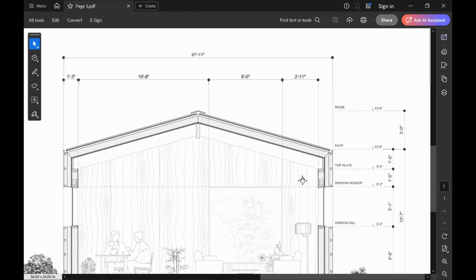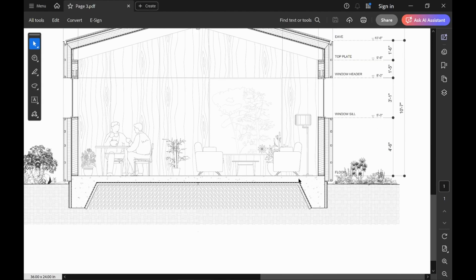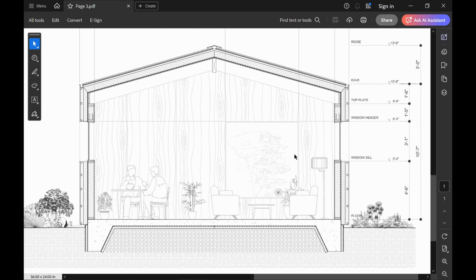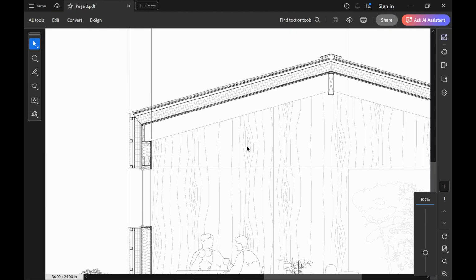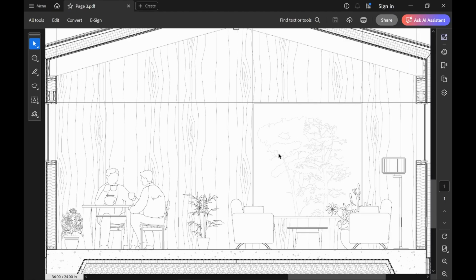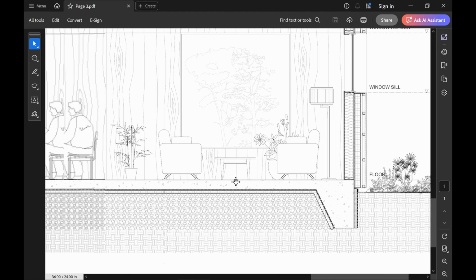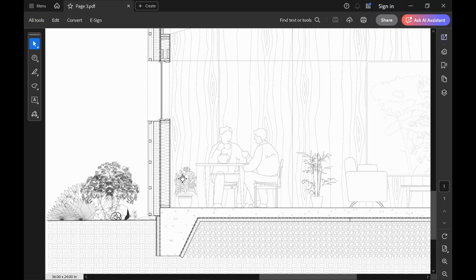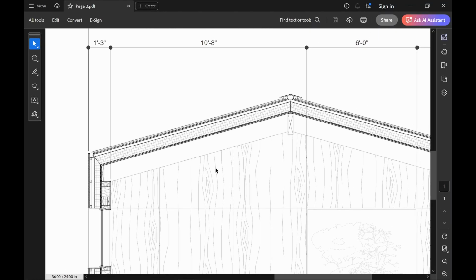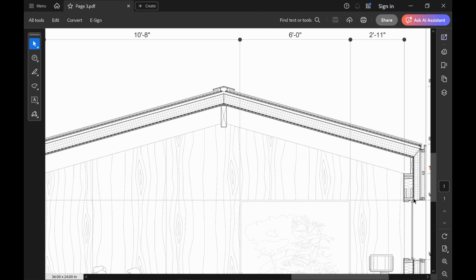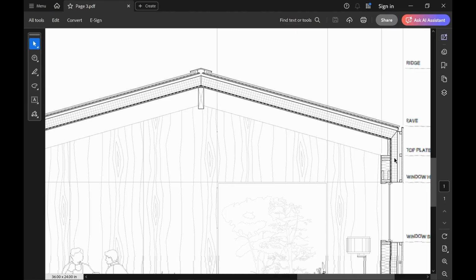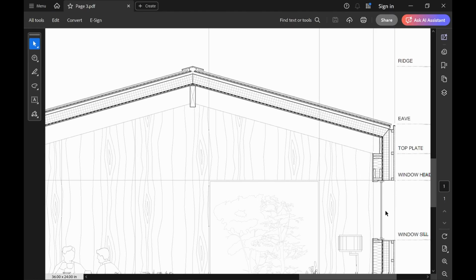But again, I think line weights look great. Hatches look great. I think the line weights look very nice at this sheet size. And I'm zoomed in very much. I can go even more. This is at 100%. You see? At 100%, things look really sharp. Looks very proportional. Like the line weights look proportional. Nothing looks out of whack. The membrane reads as well. It doesn't read that well over here. Could have made it a little bit thinner here, but membrane reads.